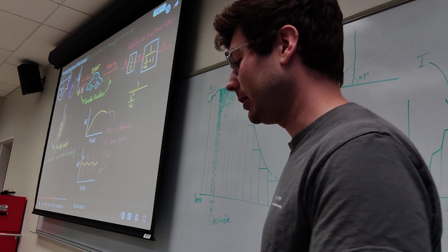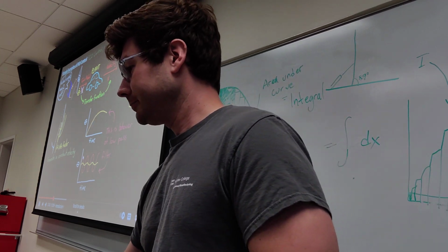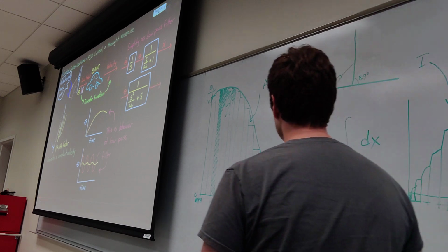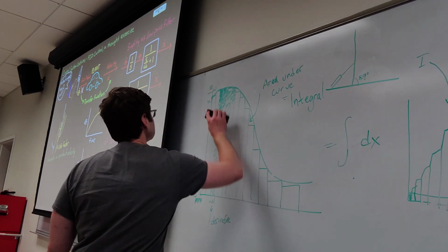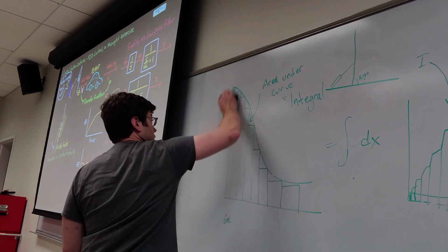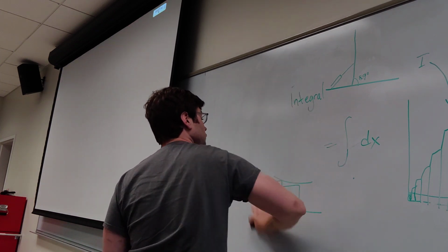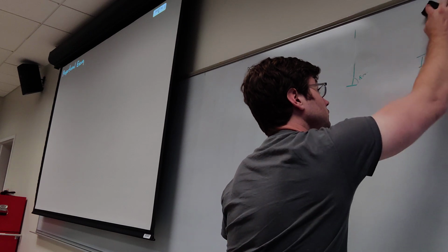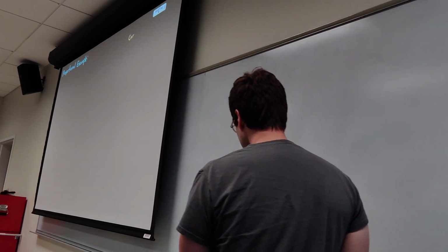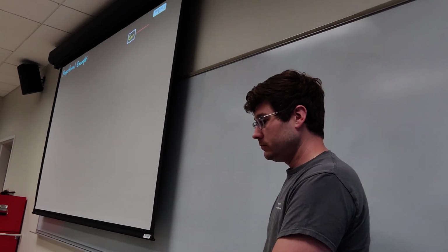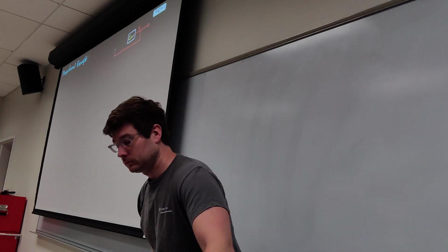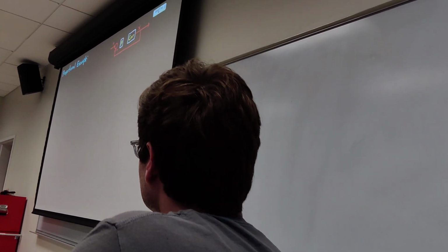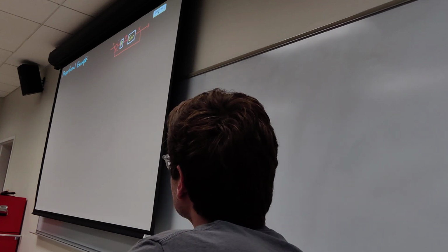The gas pedal angle to the velocity of the car is then combined and would look something like this. So keep this model in mind as we go through the exercises. In this first example, we're going to go over proportional control. The closed-loop control system for our car with a proportional controller would look something like this, where the error is the difference between our reference command and the measured signal, and the error is fed into our proportional controller.